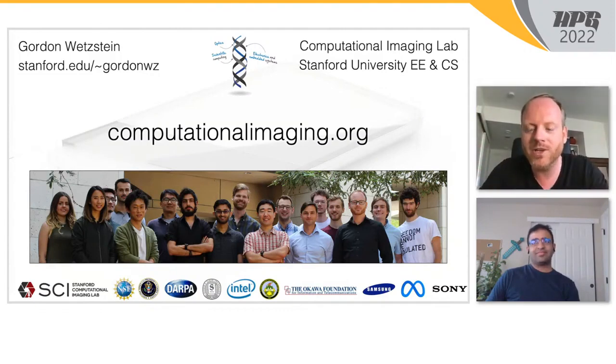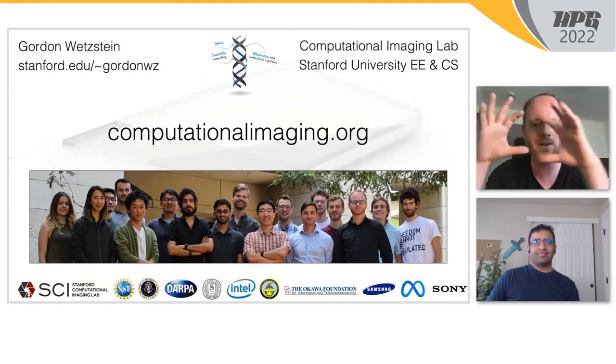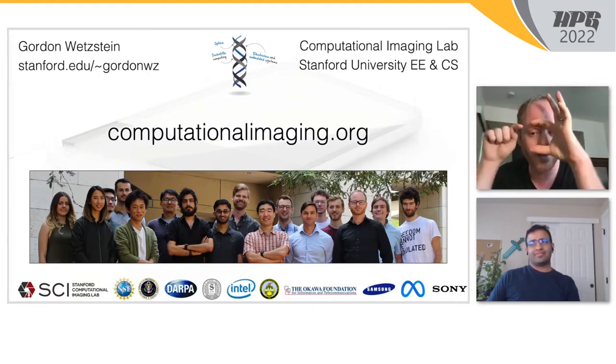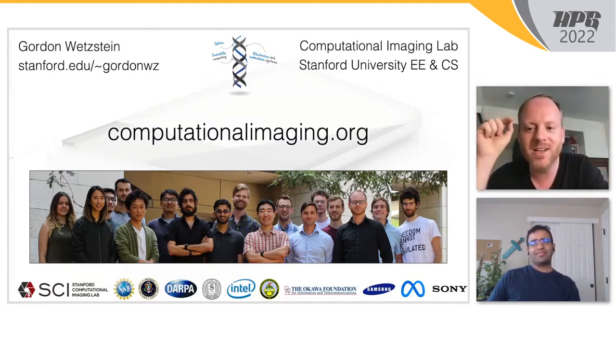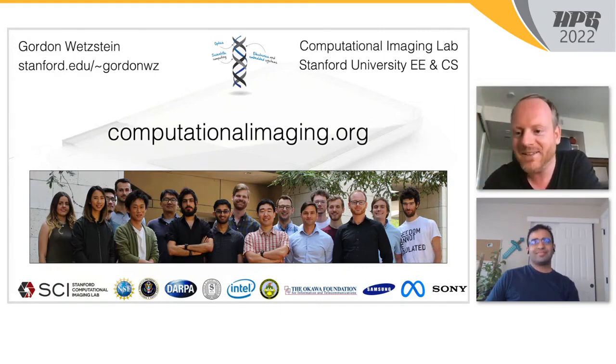And then thinking about laser beam scanning, so lots of developments on AR are out there at all the big fan companies, obviously, and some of them are thinking about using laser beam scanning, and laser beam scanning is basically using a waveguide that's very thin, using a little MEMS mirror that scans a laser, basically point by point, like raster scanning the point, like your good old CRT monitor. The thing is, again, if it's a sequentially scanned display, there isn't anything you can do in terms of saving the latency, right?